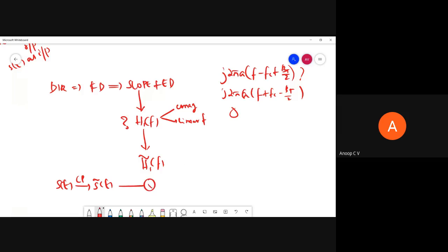So then, if we use these two, the low pass equivalent, the resultant would be actually what? Half. If there is a half here, please don't miss that, when you are transforming from band pass domain to low pass domain. In the actual time domain it was convolution, and in the frequency domain there was no half. But here we do have an extra half: half of h1 tilde of f times s tilde of f.